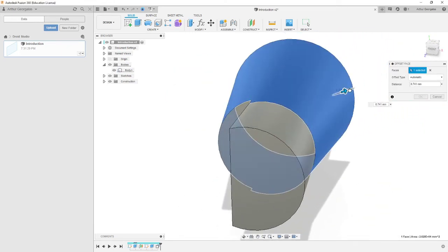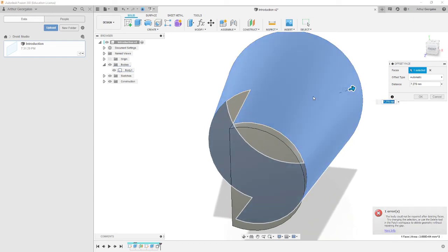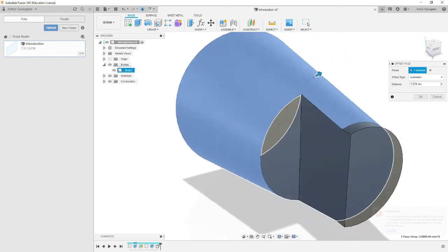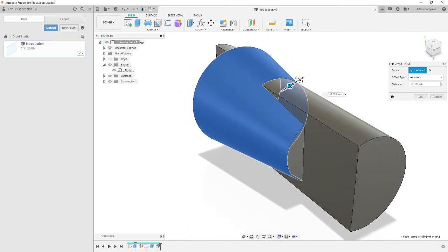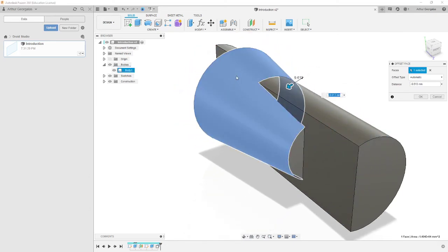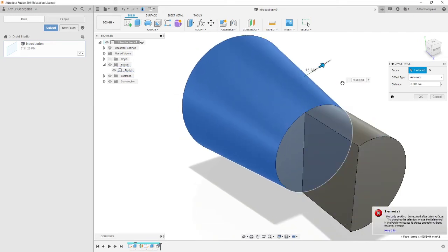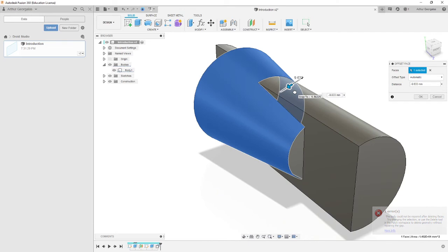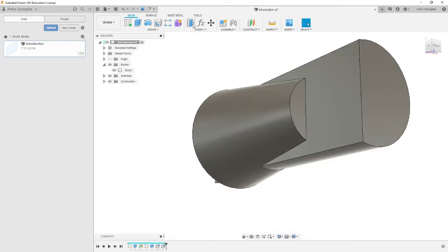Again, press pull on this surface. What it's going to do is radiate that outwards, but you might think it would have kept that line. Sometimes it's not always perfect, and it really depends on what you want. So right now, what it's doing is just changing the radius of this rear part and making everything update around it. So it can get pretty complicated and might not always do what you want.